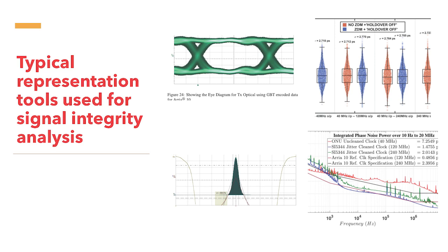The phase noise plot is used when you want to know, for a particular frequency, say for example 1 megahertz or 10 megahertz, what the phase noise is. And since these are all clock signals locked at a particular frequency, you are not that much bothered about the jitter or noise present at other frequencies. So as we have already told you, the frequency of interest is 40 megahertz and the multiples of 40 megahertz. Since I know this already in the experiment, I'm just giving you the figure for 40 megahertz.